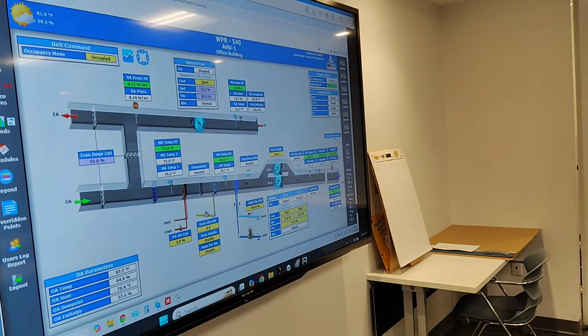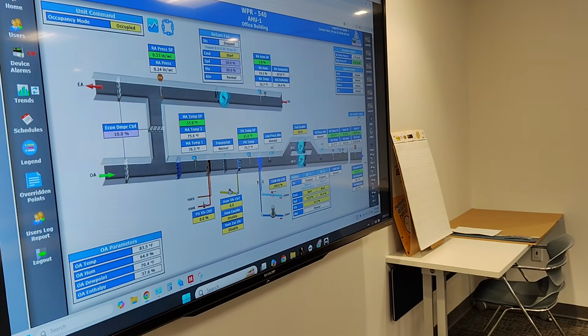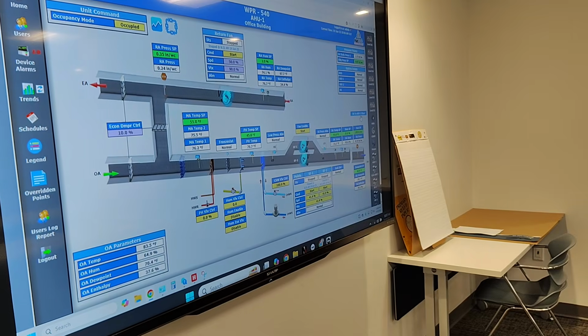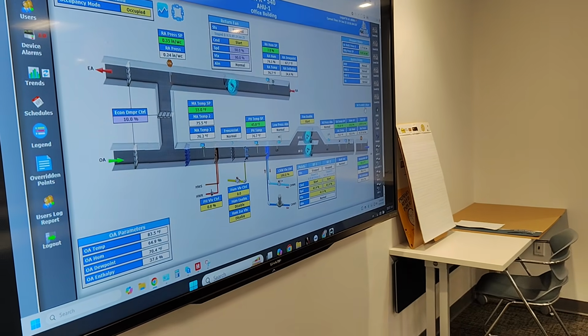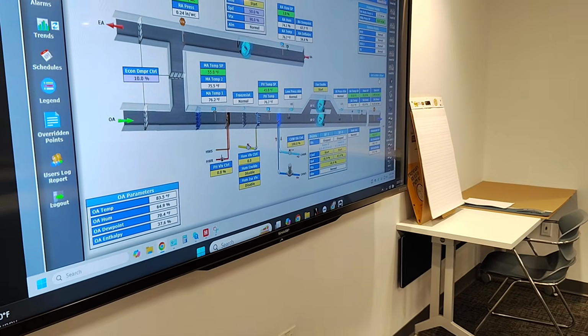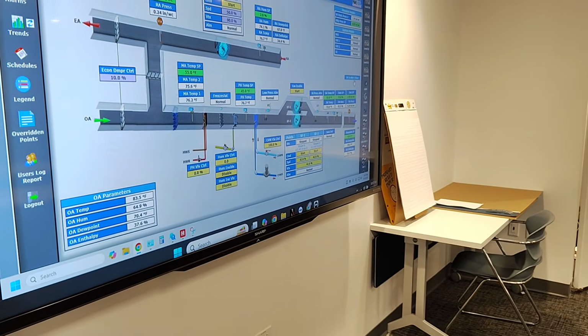So you just watched him adjust the static pressure set point to 2 inches. We're staring at those fans. They're slowly ramping. Maybe it's going to get to the 2 inches. I don't know what Siemens programs are going to do, but I just showed you that the fan speed's integrating. It's at 41, so it's climbing. Perhaps one day it'll get there. Now, it would have worked already had we programmed it. So maybe this is doing what it's supposed to do, but we don't know. All I can tell you is we've integrated. I just showed you that it's in automatic, and we made an adjustment. That's what we're talking about.